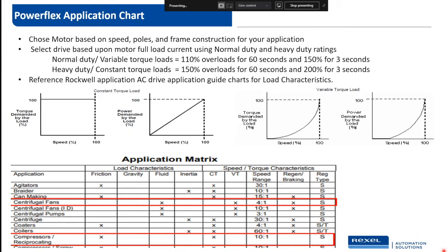So what I would do is choose a motor based on current, size it off full load current, not horsepower. Why is that? Our selector guides, if you use ProposalWorks or our online selector guide for the PowerFlex, break drives up into two classes, normal duty and heavy duty. What we don't tell you is all the charts are based off a 4-pole 1,800 RPM motor. So what happens if you have a 6-pole 1200 RPM motor, and you go to the selection charts and base it off horsepower?